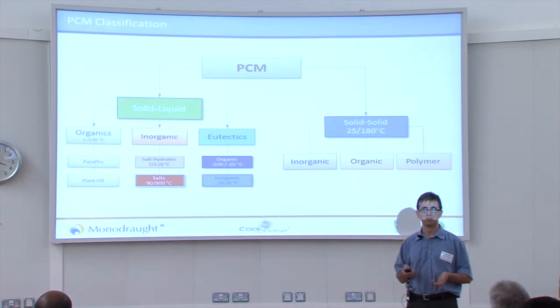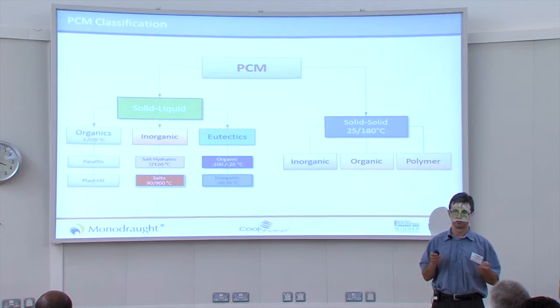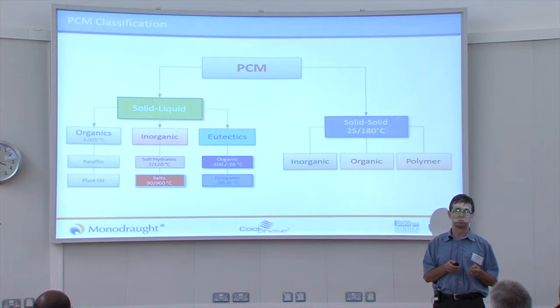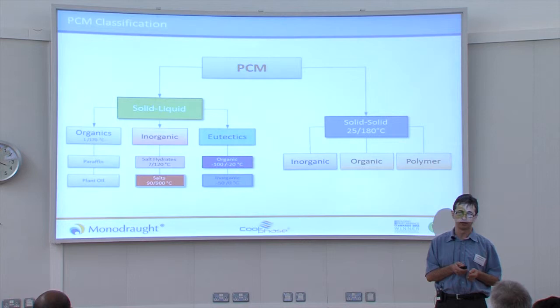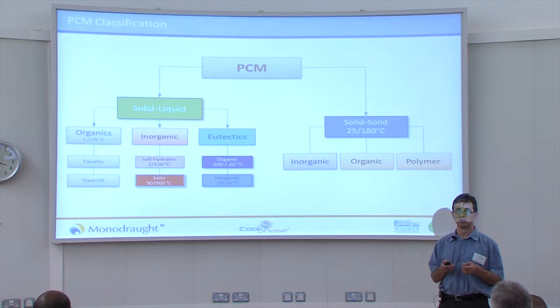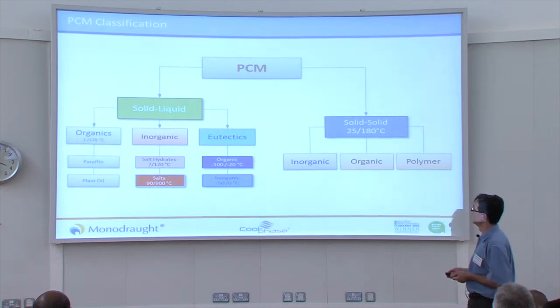Now, in terms of buildings, we have to use this range of melting and solidification, but obviously it's not good to be around 0 degrees. And that's why PCM materials are focusing on having their phase change around 20-25 degrees. Of course, if we have around 20 degrees, we have a better cooling effect, but then we are running into a problem at nighttime because we need to solidify the PCM.